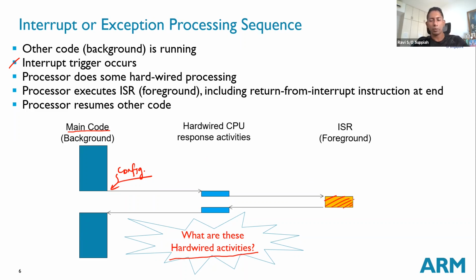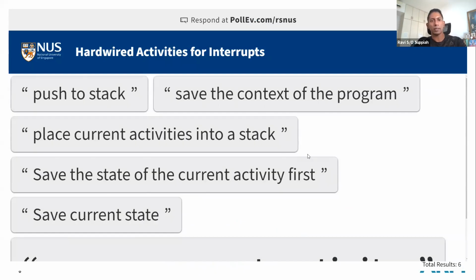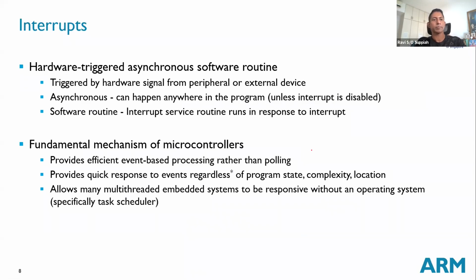We also talked about the concept of the ISR being short and focused, because you want to make sure that the rest of the backend processing can be done in the main code, or in some other tasks and so on. So that is the whole idea of these interrupts.